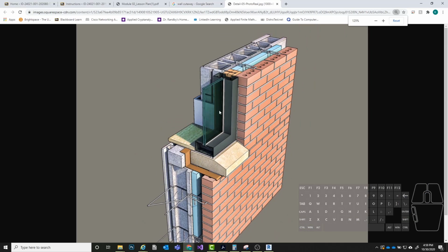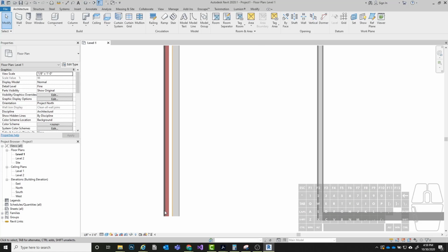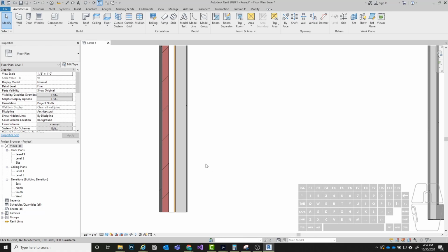So when we're looking at this in Revit, basically what we are seeing is a top-down view of this portion right here. We're seeing our layer of brick, and then maybe an airspace, our little gap right here. Then we're seeing our rigid foam insulation, then our CMU, and then our hat channel or metal stud, whatever's in there, and then the layer of gypsum on the inside. So if I toggle back to Revit, you can see that's essentially the same situation that's going on here.